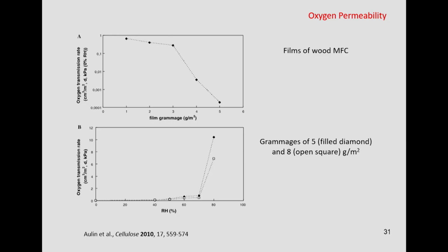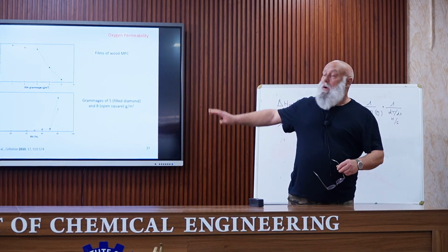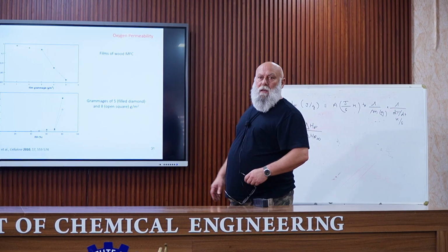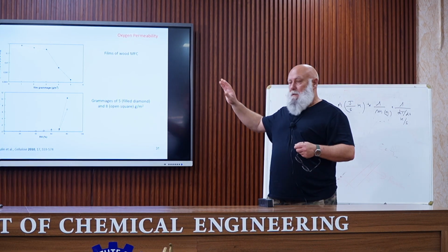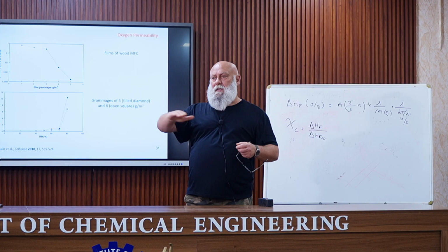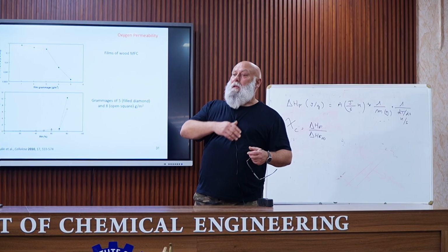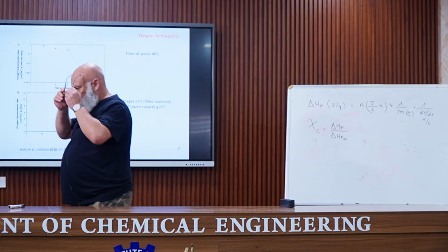But this is a problem for cellulose. It's a hydrophilic material, meaning that, of course, it's sensitive to water. One way to overcome this, which I think I already mentioned briefly, is to use a film of cellulose nanofibrils, for example, that provides the oxygen barrier properties, and to protect this film from moisture using another layer that can be wax, or a hydrophobic polymer, and so on.